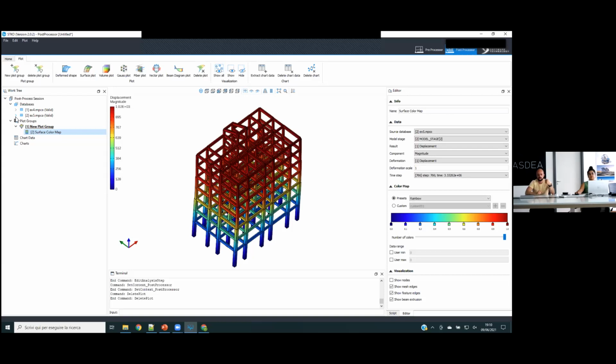They are called follower loads, but typically they are used only in mechanical software where you have very large deformations. So if you have, for example, a load acting on a beam and the beam bends a lot, and the load wants to remain normal to the surface, and the beam bends, the direction of the load should change. Yeah, because I'm studying stability.